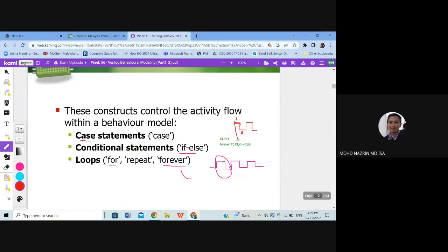is, you look back here, the clock period is actually 10 time units. Why 10? Because we set 5 here. It means it inverts every 5 time units. So high, and then it inverts to low. So a complete cycle of the clock is a total of 10.